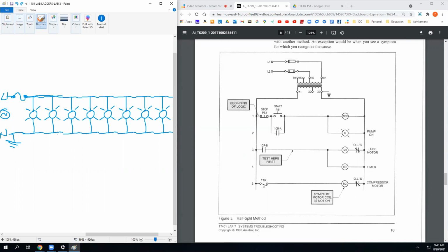You can check that and that's fine, but that's not going to show you where the ground fault is, right? Somewhere in this line up here, something is leaking to ground. It could be here. It could be here. So do you start with the first one or the last one? You could guess. You could be right the first time, or not. You actually start in the middle. What were you going to say, Heath? I was going to say, if you're using a half split, if you do in the middle and you can't find the problem, everything past it obviously doesn't.